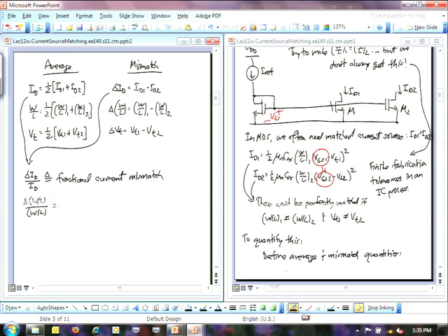In this, I can pretty much identify here my average overdrive voltage, VOV, VGS minus VT. I'll just note that now, but not really use it at this point. Now what I'm going to do is try to expand this. Here I'm going to have 1/2 mu n Cox. Nothing to expand here, so I'll just repeat this down. Now I'll expand the square term.